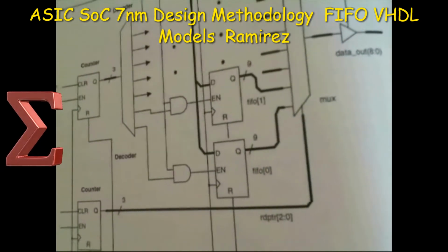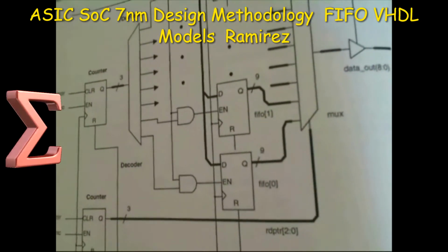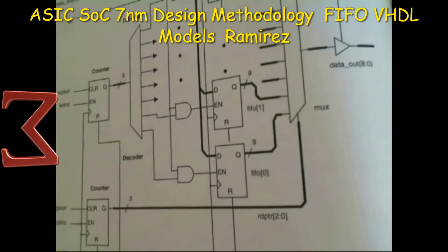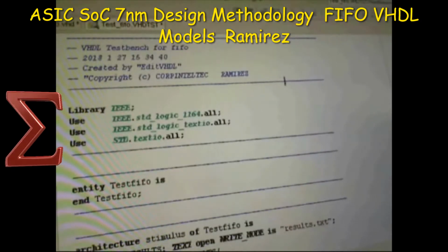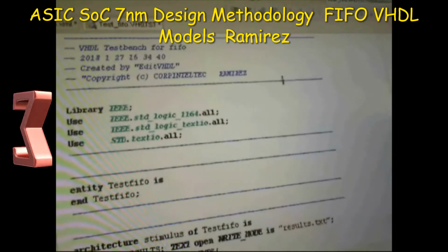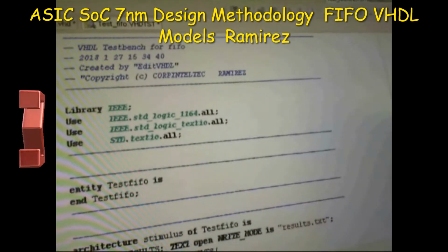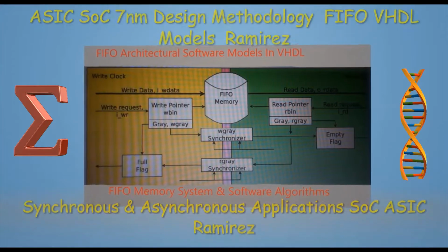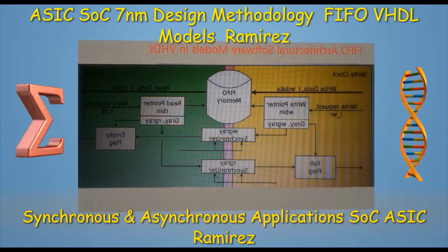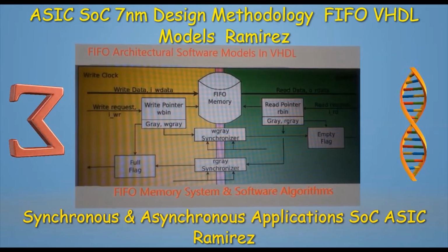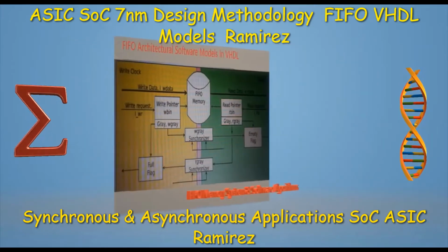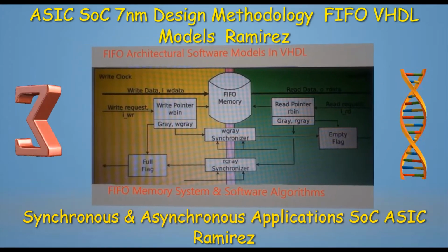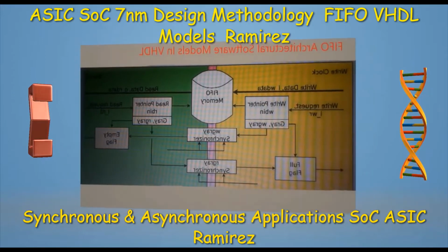When the full flag goes high, the FIFO's memory is full and will not accept any more writes until data is read using the read enable input. This process is illustrated in the VHDL architectural software model as I have presented in this video.